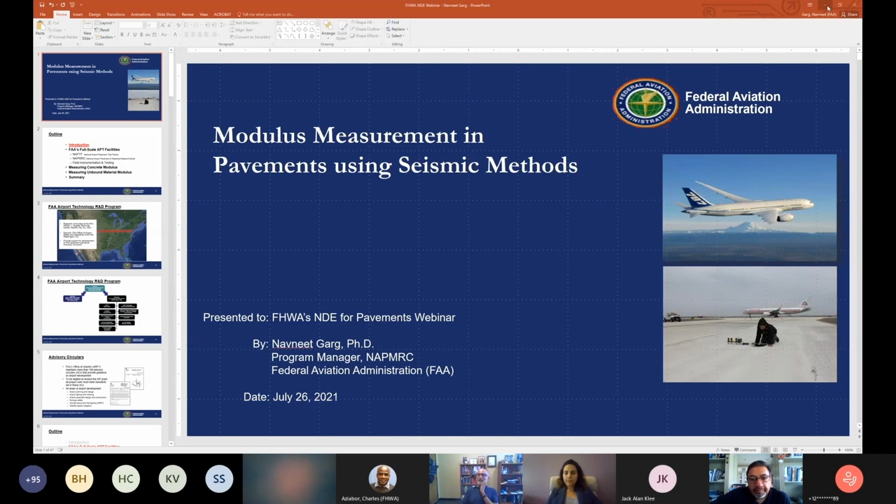Next question, does this method compare to ultrasonic P-wave methods on concrete? Sohail? Yeah, theoretically it should. We feel that surface wave is more robust than the compression wave for this purpose. But under the same circumstances, they should give you numbers that are related through Poisson's ratio directly.